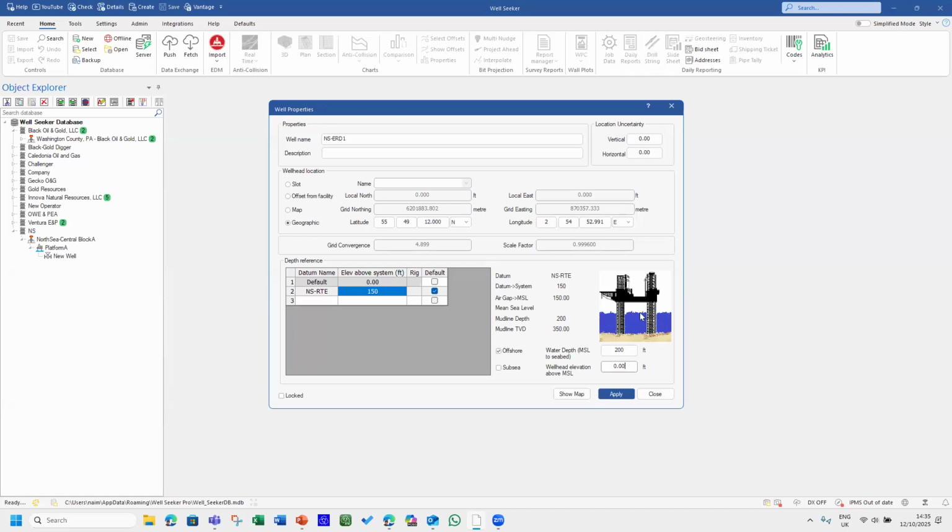It could be off by 10, 20 feet. Nobody knows. So air gap has a slightly different definition. You need to find out which one you need, which I have mentioned to you, rotary table elevation. If you get this wrong, all your surveys and TVD surveys will be off by that much, 20 feet off, 15 feet off. So that's something that you do.